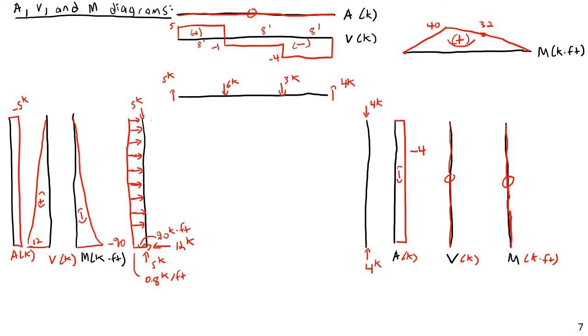Usually I label my columns like column AB, column CD. But whatever your naming convention is, you have to define a 0 end of the beam. As if you're doing this by integration, you would need some point that was the 0 x value, and in turn, that defines what your overall positive and negative bending moment are.